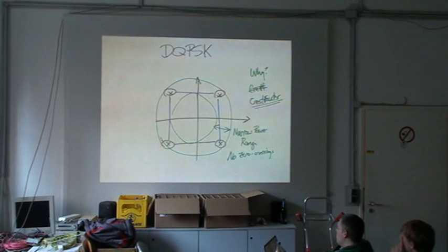A linear power amplifier is a device that draws constant power. Some of that power at any given moment is being diverted into the antenna, and the rest is being converted to heat. That means that whatever the maximum peak instantaneous power of your signal is, your amplifier has to be able to generate that much power at any given moment.